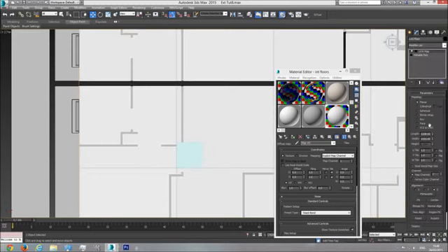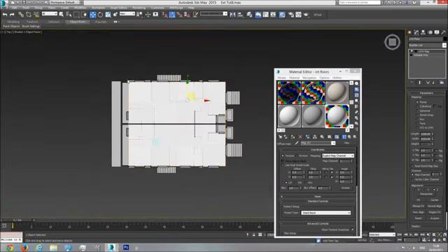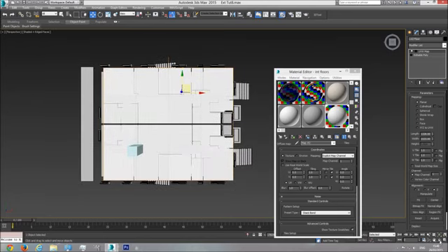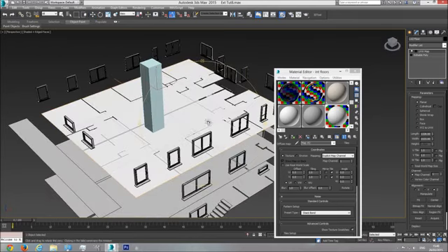floor again, and it's on planar now, which means it will only do a 2D representation of the map, so it's flat like the floor, which is good for us. If we want to texture a box like this, if I use planar, it will texture the top part but won't texture the sides, and that's because planar uses a 2D plane to align the texture on it.